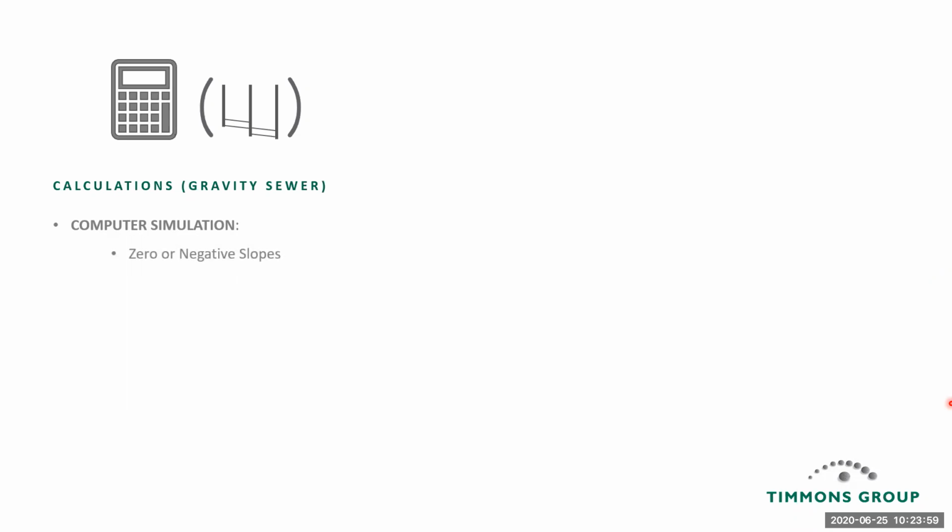Again, 0 or negative slopes, extended period simulations where we can monitor the fluctuations of flow depth over the course of either an hour or a day or several days. And then we can also use it to identify surcharging or potential overflows.